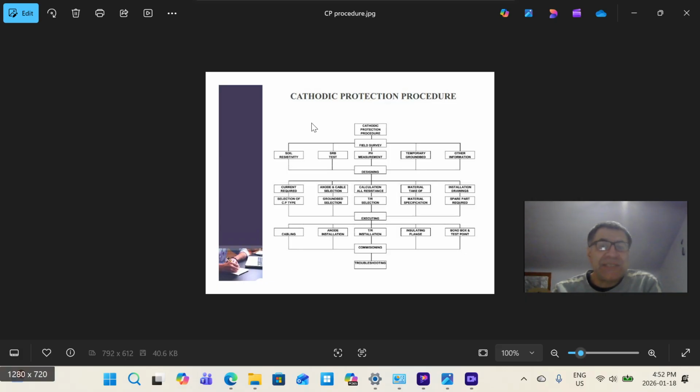then we should design the cathodic protection system by finding how many anodes we have, what is the minimum distance between each anode, what is the capacity of the rectifier to provide the power, what is the weight of each anode, the type of the connection between anodes and the pipeline, design the welding between the cable and connection cable between anode and pipeline, and size and grade of the current cable. All the system must be designed.